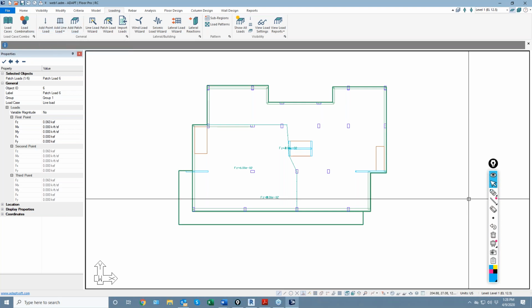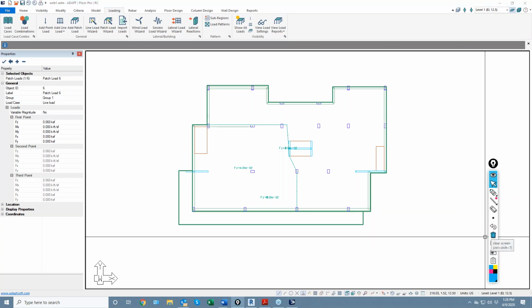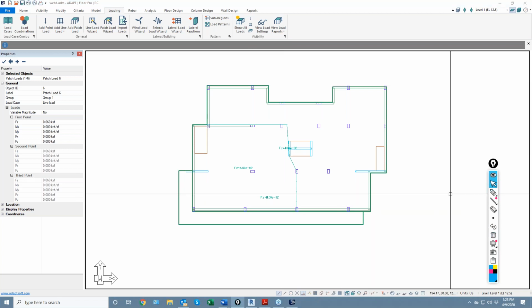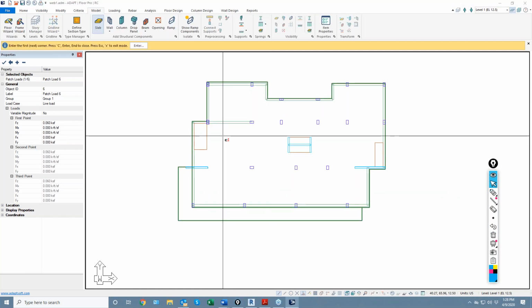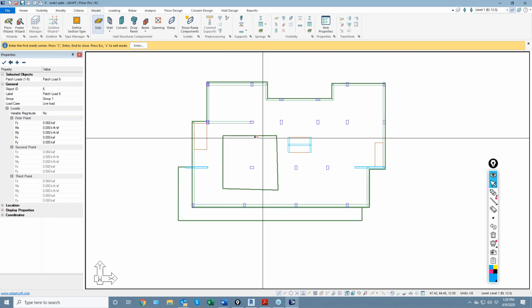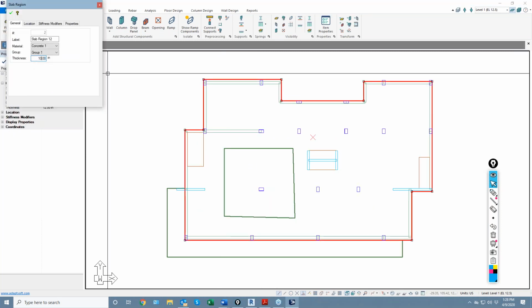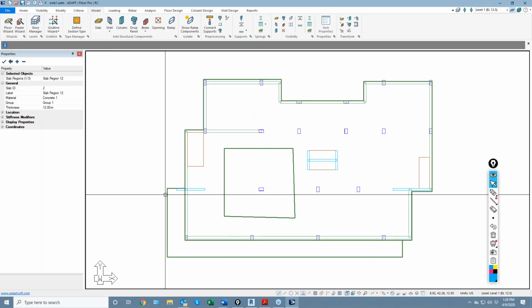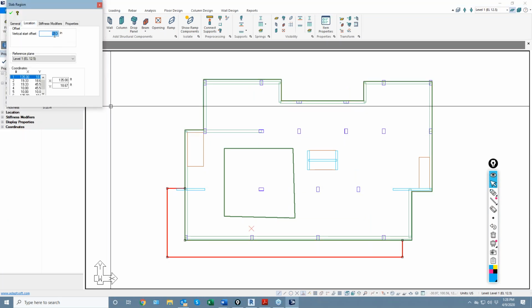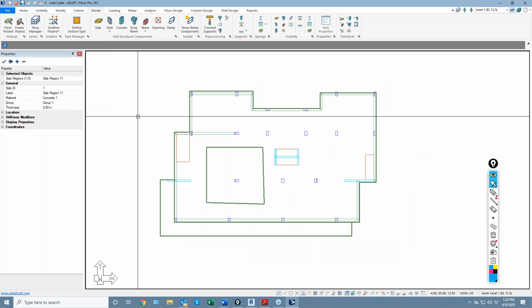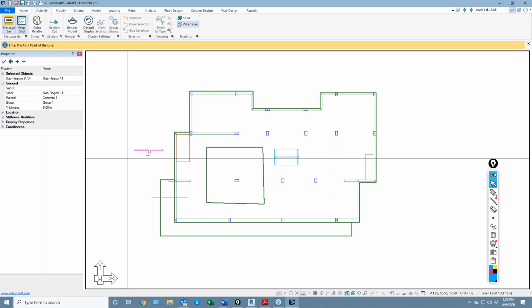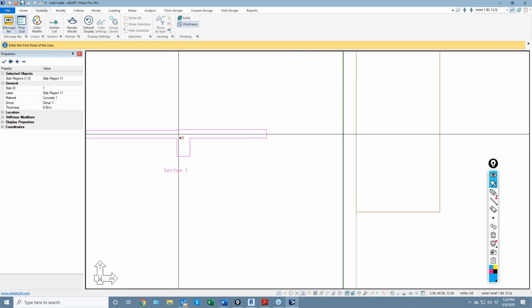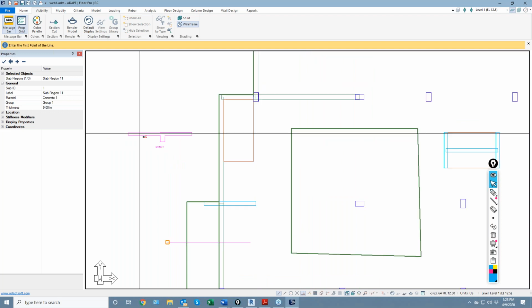So one thing to watch out for is if you have a slab setup where you have nested slabs. So let me go ahead and show an example here. If I put a slab inside of this slab, I'm going to change the slab thickness here to 10 inches. And I'll use a 9-inch slab, and we're going to use a 1-inch offset. So the vertical offset positive is downward. If I take a section cut under my visibility panel through this section, you can see there's my beam. Here's my little step, that 1-inch step into a balcony for that location.